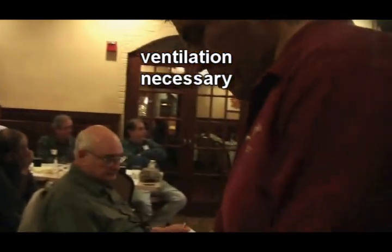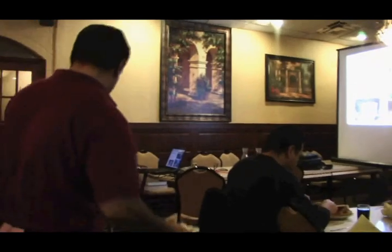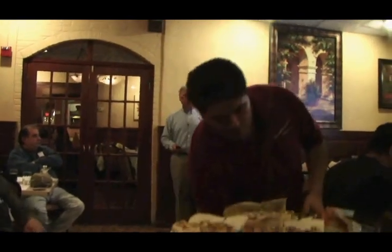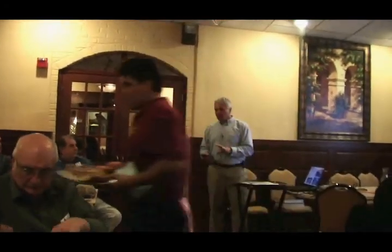A lot of machines. The picture before showed an open set, meaning it did not have an enclosure on it. Those machines are typically used in a shed. So ventilation is big, whether it's indoors, in the basement, or outdoors in a shed, or you still find many machines in garages. They need to be ventilated, not only for cooling air, but exhaust. Big thing, exhaust.